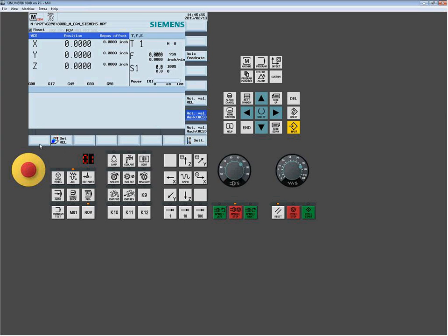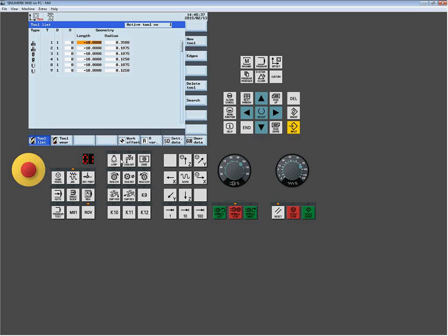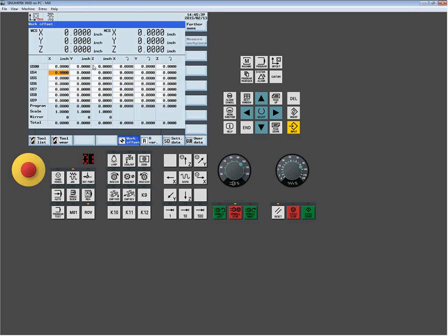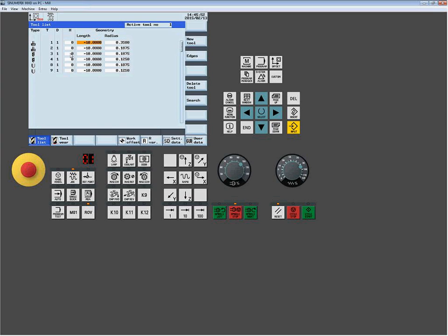I'm now set up. I said it earlier, just a pic on the PowerPoint, but here you can start to see the buttons are now missing, and that's because you're in ISO mode. You have the ability to set relative zeros, but if you want to actually write to any offset tables, you have to physically go to the offset table, work offsets, and enter what the offset value is. And that would be the value right here, this machine coordinate system value. Now, very important, you get the H column.